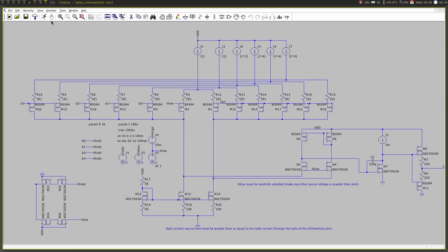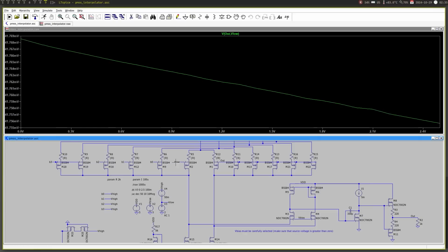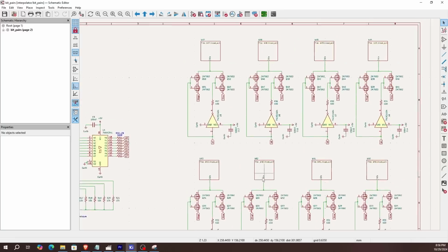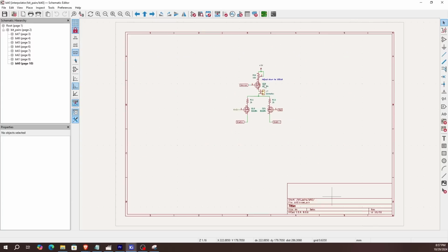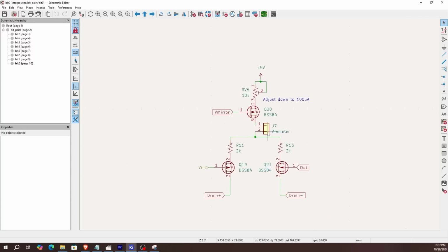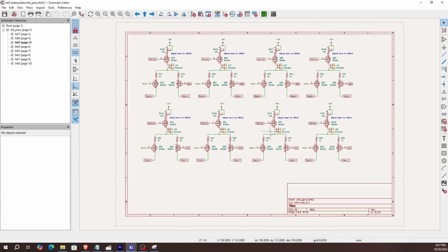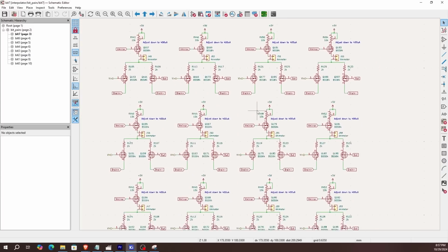This whole design works really well in the simulator, but it most definitely won't work like this in real life. Remember how I said that linearity is affected by how identical each pair is? Well, in real life, we have to worry about the matching of each Mosfet in each pair. This isn't that much of a problem for integrated DACs, since they are all manufactured on the same silicon, using the same process, which means that the matching errors will be minimal. But we will be making this out of discrete transistors, so we won't have that advantage.